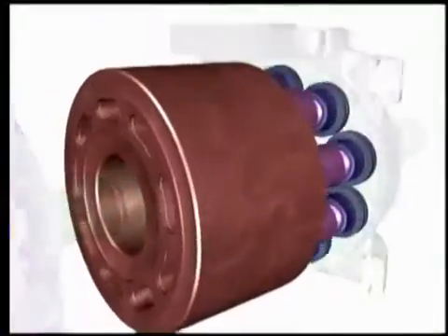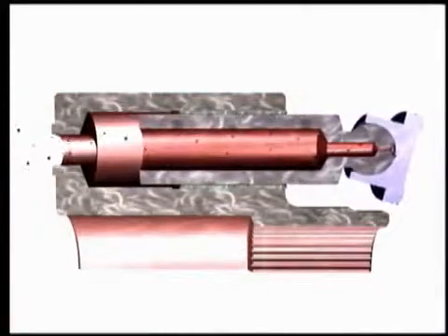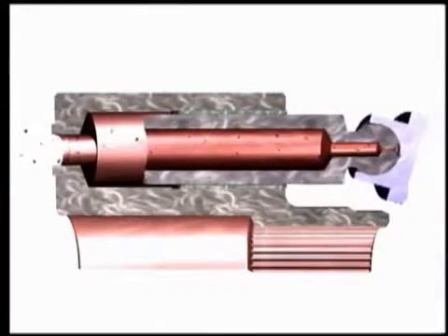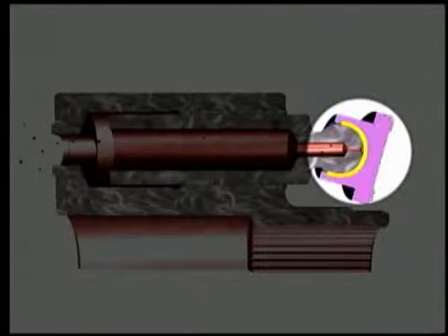As we look at other ways contamination can cause problems, we turn the animation of the pump 90 degrees onto its side. Particles can lodge between the piston and the brass slipper foot, seen in purple, causing it to jam. Or the contaminants can scrape walls between the barrel and piston.